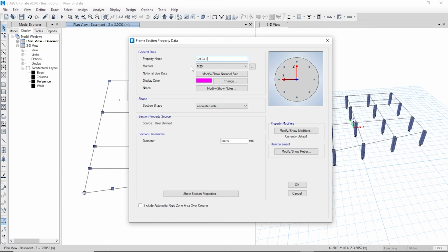For example, a simple 2 rods of 25 mm dia bar in a column costs the same as concrete required to fill up the entire column. Not only do these checks increase the steel in the column, they also prompt engineers to increase the size of the column so that steel quantities can be brought down. So how to overcome this problem of high steel in columns due to these checks?